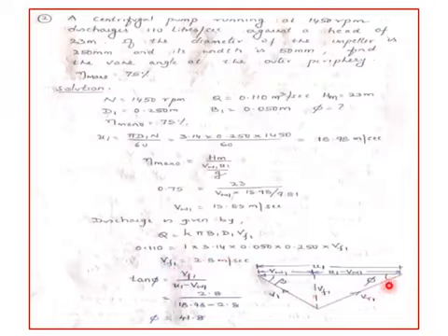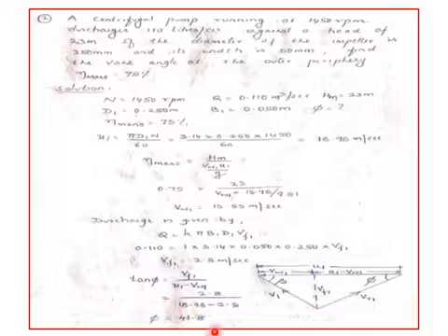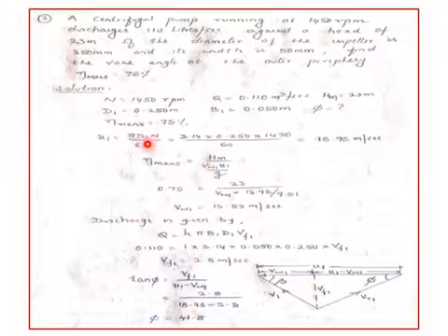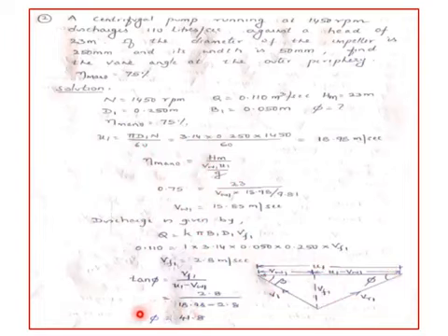So now you can draw the velocity triangles. Hence tan phi is Vf1 by u1 minus Vw1, where the vane angle at the outlet is 41.8 degrees. So this is how you solve the problem. Make use of the discharge equation here, make use of the manometric equation, and then write the velocity triangles and solve for the vane angle at the outlet.